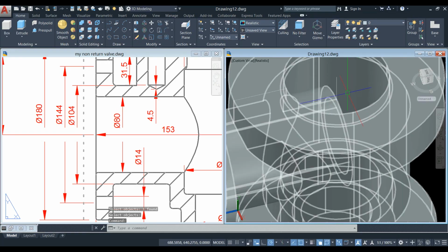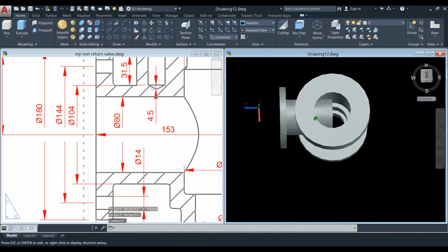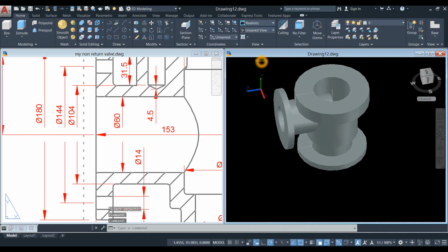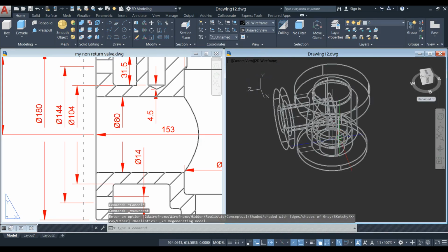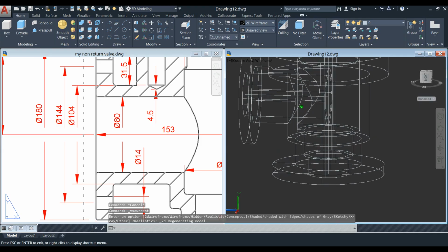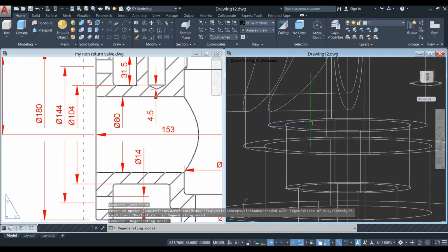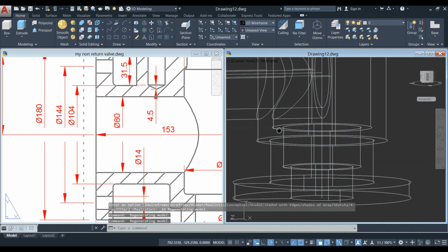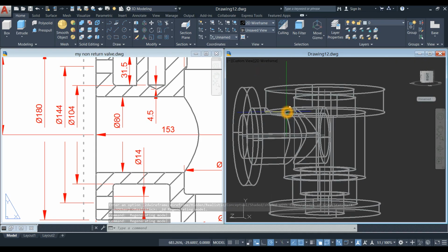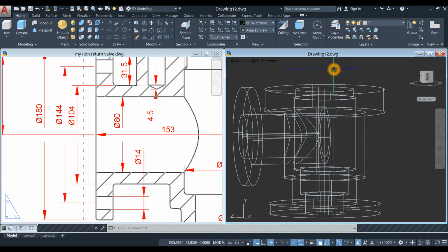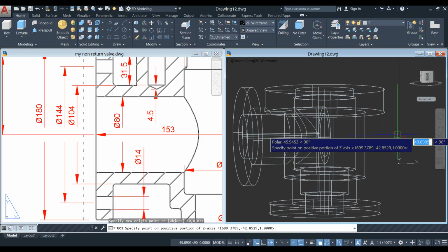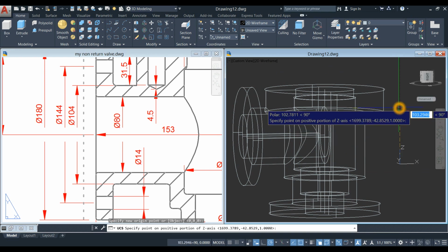Now to remove this portion here that's sticking out, I'm going to change this to 2D wireframe and create, so it should cut from this point here and bring it upward here. So I'm going to create circle. I'm going to change the direction of the Z first, parallel to the direction of the circle I'm making, or the cylinder.